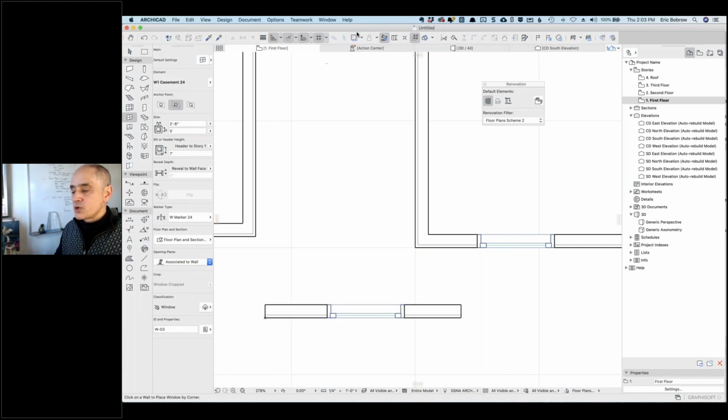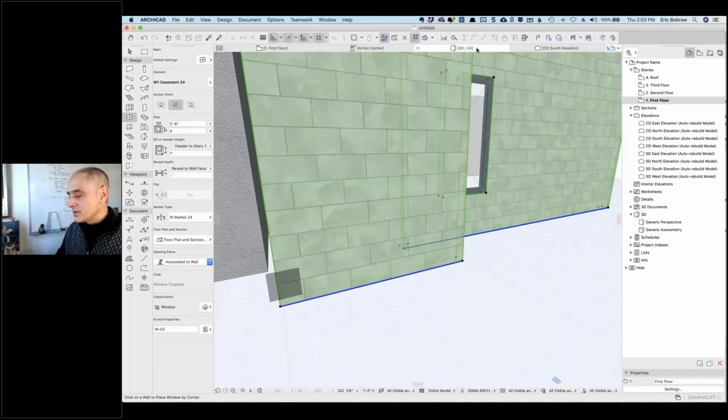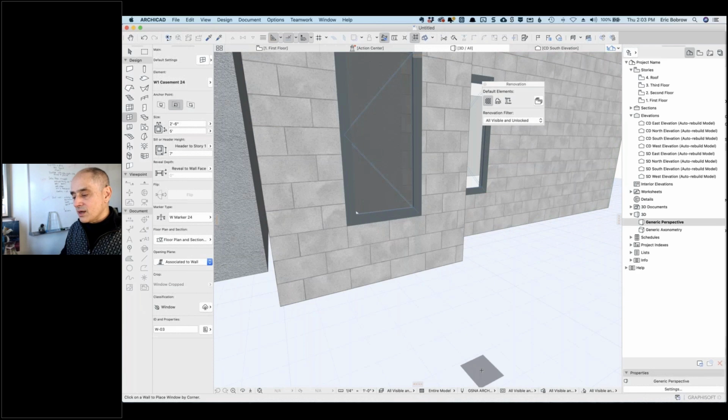So in order to move that around to a new place, I turn off the grid and put the origin on a point, like this, and then turn the grid snap on, and now it's going to be in relationship to that. So this origin point is a way of setting the snap grid origin. So that is a very powerful thing to do, and the ability to move the texture origin. And let's just go back to 3D, and we'll see that now this window is precisely snapped in on a unit there. Now the end of this was not set, I just drew it arbitrarily.